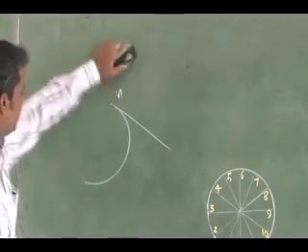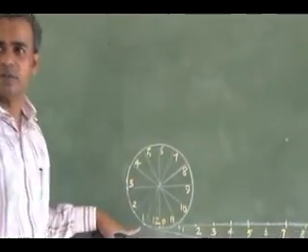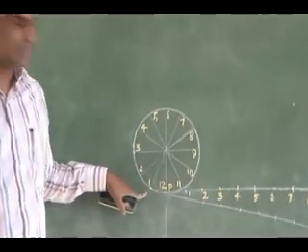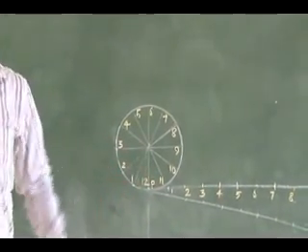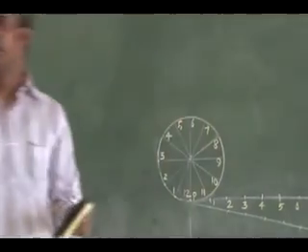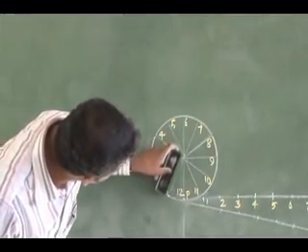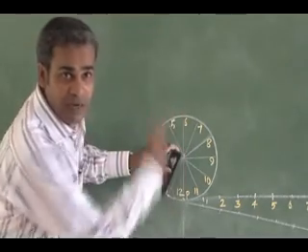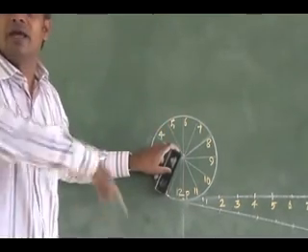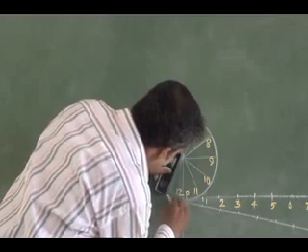In the same fashion, from 1, 2, 3, for all the segments I have to draw tangent lines in the negative direction. I can keep my drafter, with one scale along the segment line 1, and the other scale will be perpendicular. Using that scale I can draw a tangent line.